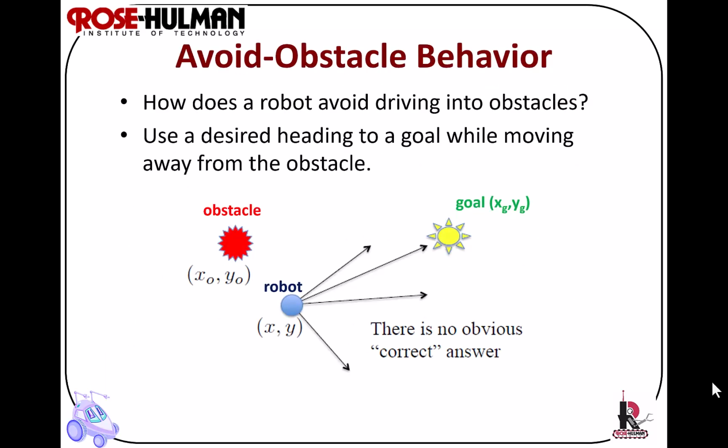So think about what avoid obstacle means. There are several ways to avoid an obstacle. One way, if the robot is moving, is just to stop. The other way is for the robot to move away from the obstacle. There are various ways to do this, and the way we're going to do it is potential field navigation. And then in a couple of weeks, you're going to see that we're going to integrate smart wander or avoid obstacle with go to goal, where your potential fields now have not only a repel force, but also an attract force, where you're repelling the robot away from obstacles, but you are drawing the robot into goals.